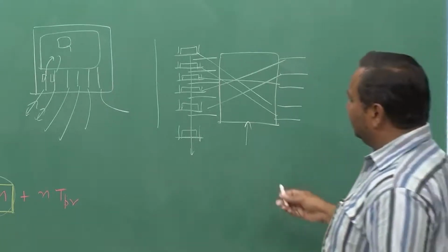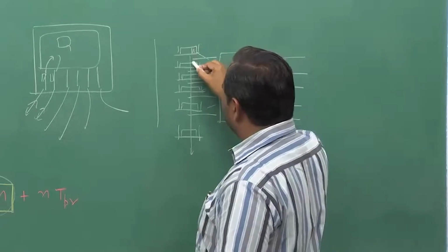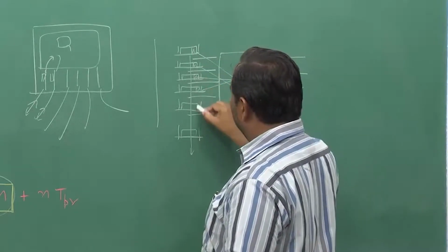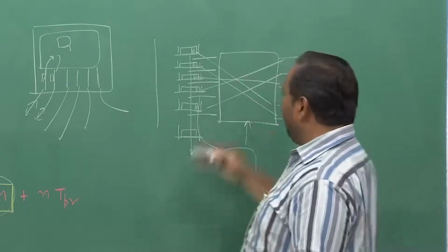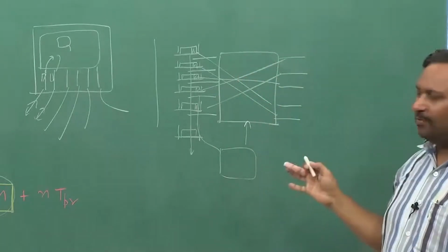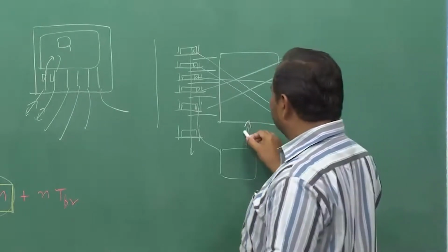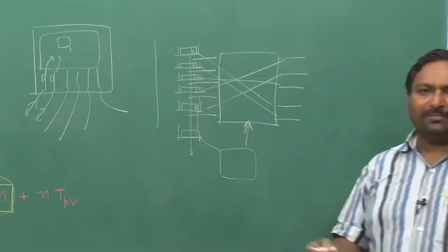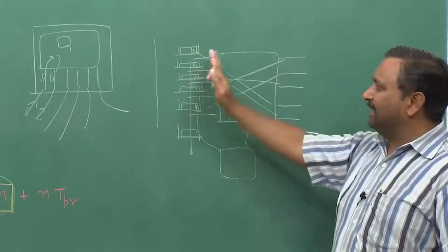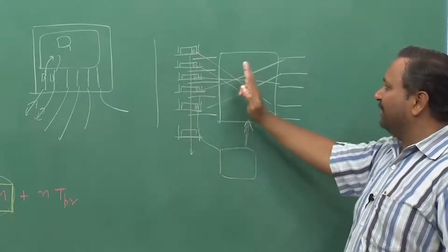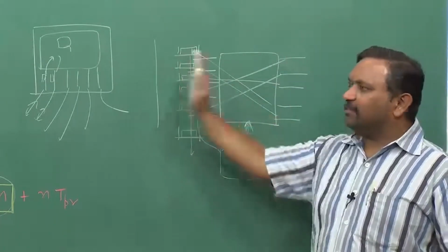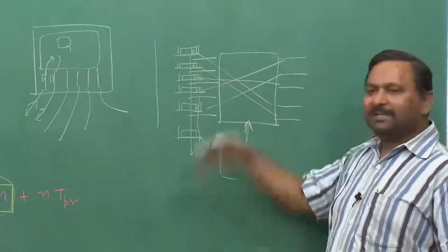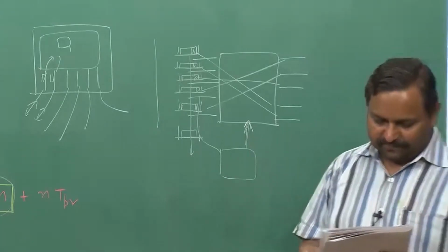So the idea is that you now look into the headers of all these packets. These have to be analyzed by somebody. A map has to be decided for how the crossbar is going to operate. It has to exert the control, that row and column control. Once that is done, by the time the packet comes up, the packet will be passing out to the output, and then the next set of packets will be coming in. Again the same procedure, you will keep on doing it.